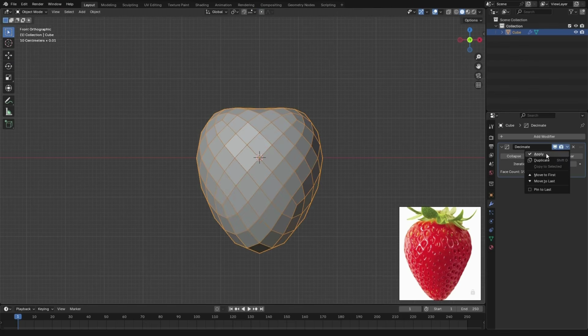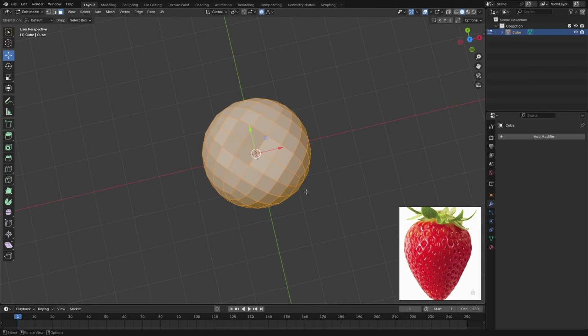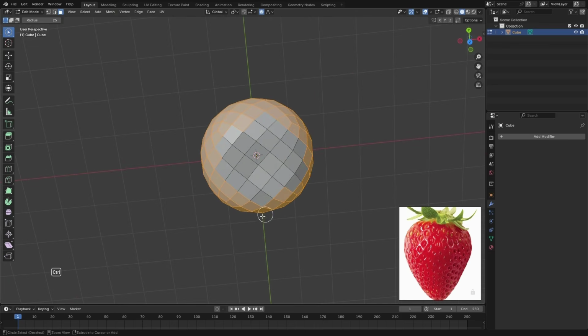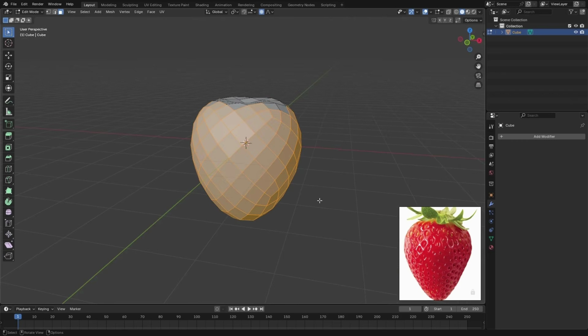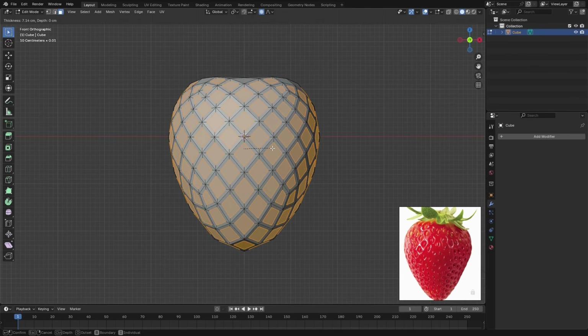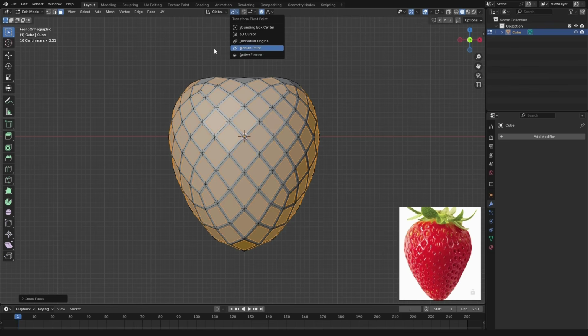First of all, apply this decimate and hit A, grab everything, but in the top view, exclude this top part. You see, there's no seed up here. So let's switch to a circle select, hold Control and deselect these parts. Let's go to the front view and hit Insert, I, and I after that. So 2I. Insert, first I, second I is for individual selections. Or simply, before hitting insert, use this individual origins.